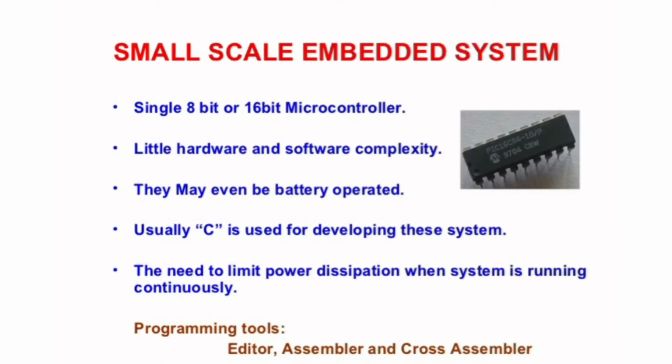A small scale embedded system is built around a single 8-bit or 16-bit microcontroller. Little hardware and software complexity is involved. They may even be battery operated. Usually C language is used for developing these systems. These systems need to limit power dissipation when the system is running continuously.